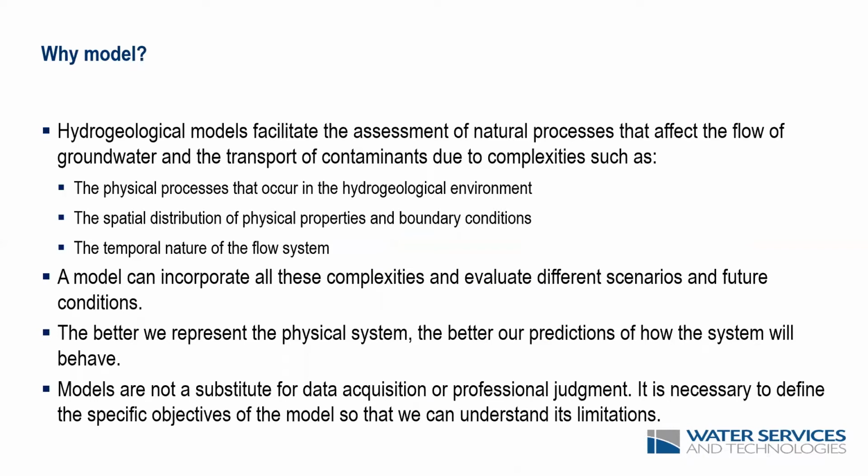So going to today's topic, why model? Hydrogeological models facilitate the assessment of natural processes that affect the flow of groundwater and the transport of contaminations in complex environments, which involve the physical processes that occur in the hydrogeological environment. So we are looking at groundwater flow controlled by advection, but also, in terms of contaminant migration in the subsoil, things like dispersivity and diffusion, which are relatively complex mechanisms to be dealt with only analytically.